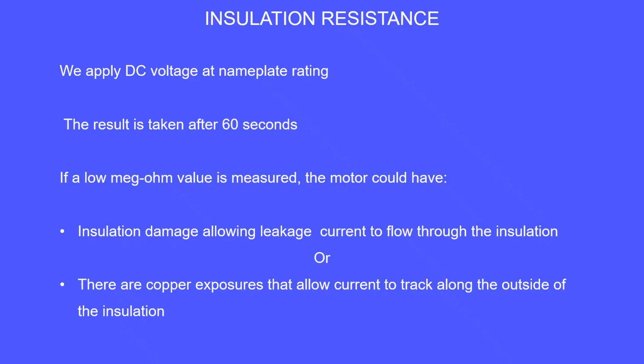If a low megohm result is measured, the motor could have insulation damage, allowing leakage current to flow through the insulation, or possibly copper parts such as connectors that are not sealed, allowing current to flow along the outside of the insulation. This is known as surface leakage.